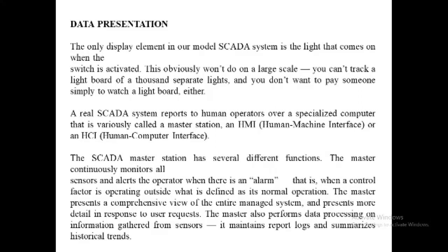For most analog factors, there is a normal range defined by the bottom and top level. For example, you may want the temperature in the server room to stay between 60 to 85 degrees Fahrenheit. If the temperature goes above or below this range, it will trigger a threshold alarm. In more advanced systems, there are four threshold alarms for an analog sensor, defining major under, minor under, minor over, and major over alarm.